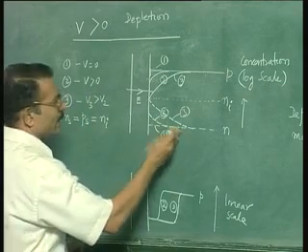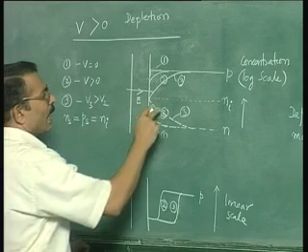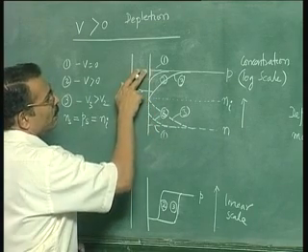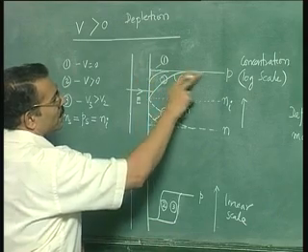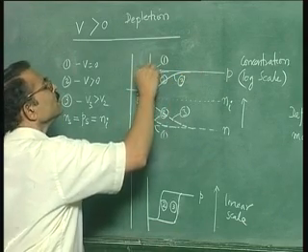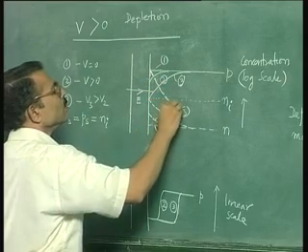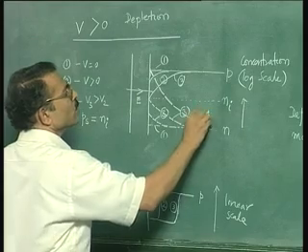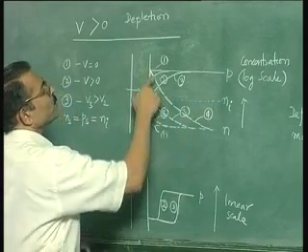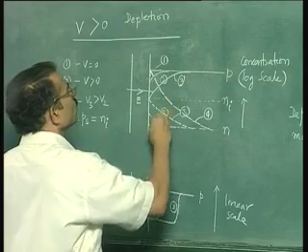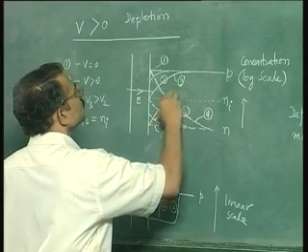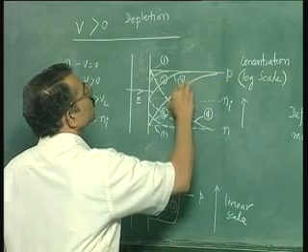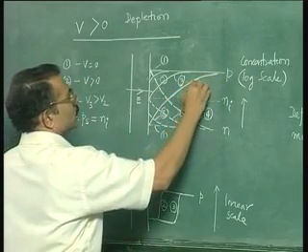Now you can go to even higher voltage, and at some voltage this electron concentration will become equal to the hole concentration in the bulk. Let us draw that condition. So this is 4, and corresponding to this 4 electron concentration, the hole concentration would be something like this. So this is 4.